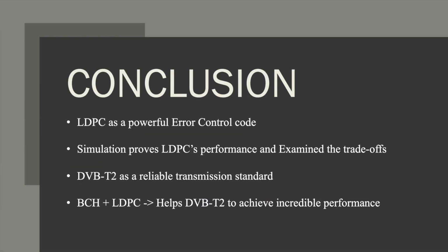To conclude, in this project, the fundamentals of digital communication systems, LDPC codes, and their role in the DVB-T2 system are studied. Simulations are analyzed and provide support for LDPC as one of the most powerful error control codes. With fixed code length, higher code rate will lead to higher bit error rate due to the decrease of parity bits.